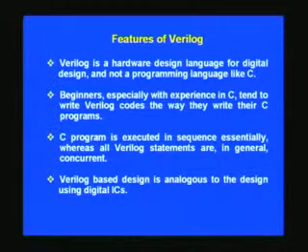We have already seen that Verilog is a hardware design language which is very much akin to C, but we should bear in mind Verilog is a hardware design tool and not a software design tool, whereas C is clearly a programming language which basically runs sequentially unless you veto it by calls and the rest of it. Whereas in Verilog, although it resembles a C program, you should know that they are all concurrent statements. So it is precisely the same as a digital circuit design, making use of the conventional TTL gates.